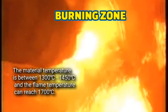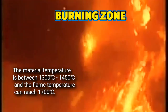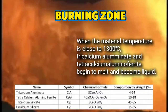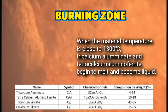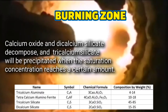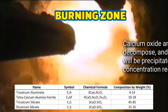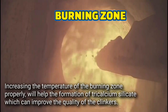Burning zone. The material temperature is between 1300 to 1450 degrees Celsius, and the flame temperature can reach 1700 degrees Celsius. When the material temperature is close to 1300 degrees Celsius, tricalcium aluminate and tetracalcium aluminoferrite begin to melt and become liquid. Calcium oxide and dicalcium silicate decompose, and tricalcium silicate will be precipitated when the saturation concentration reaches a certain amount. Increasing the temperature of the burning zone properly will help the formation of tricalcium silicate, which can improve the quality of the clinkers.